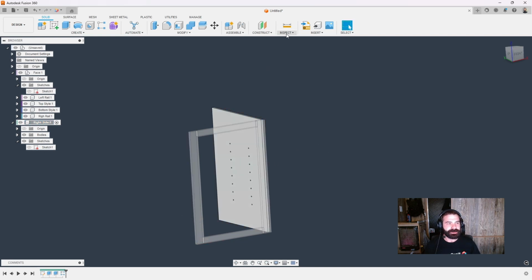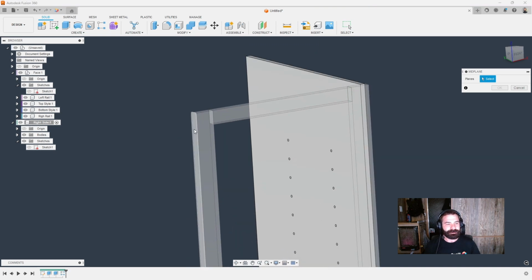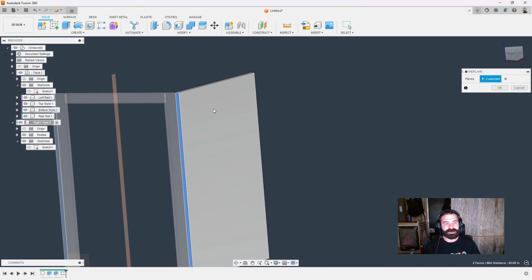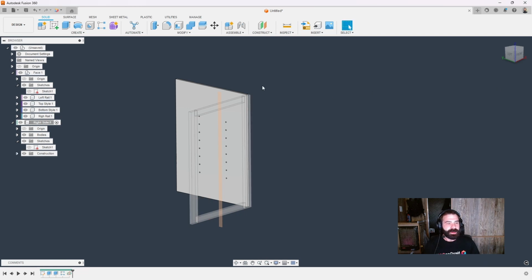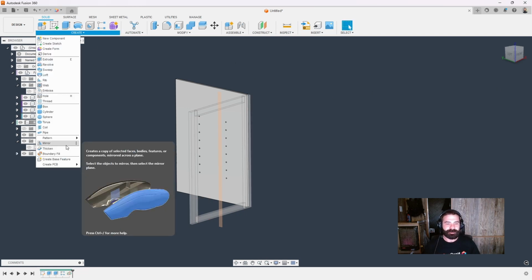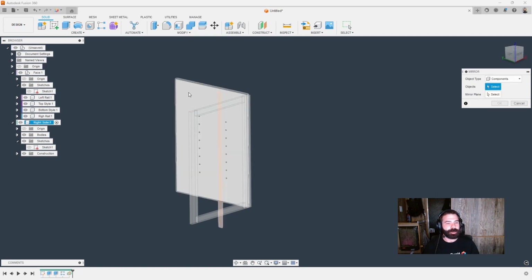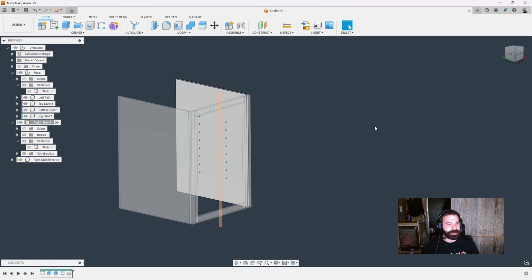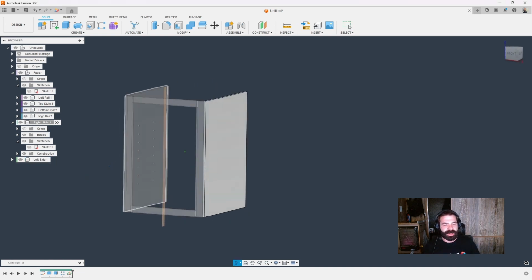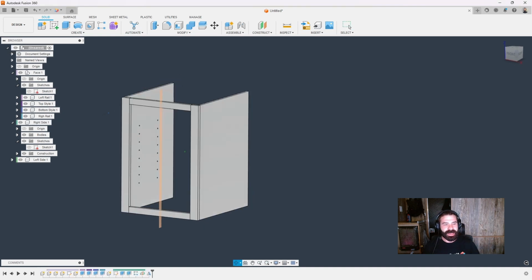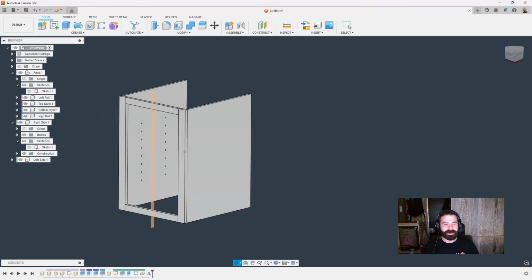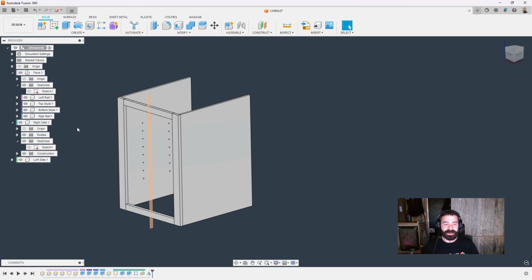So let's go ahead and cancel. Let's go back and create our own mid plane. And we can create that mid plane based on the left and the right side of our faceplate. And then we're going to use that actual plane for our mirroring. So again, is why we're going to go ahead and pull that component. We're going to go ahead and use our center line to mirror our left and our right and hit OK. But the nice thing is you now have your right side and your left side. And again, these are ambidextrous parts. So when we mirror them, you're going to notice that all of our dowel pin features have come through, again, from one side to the other, making life extremely easy for everything and anything that we do.